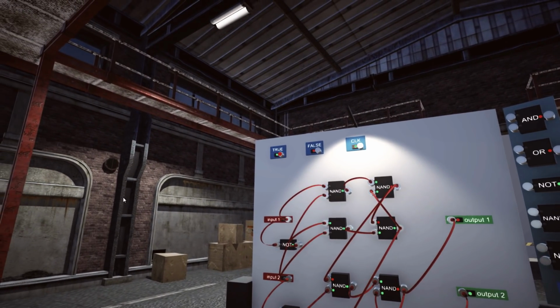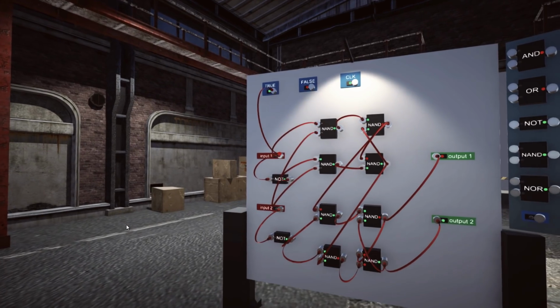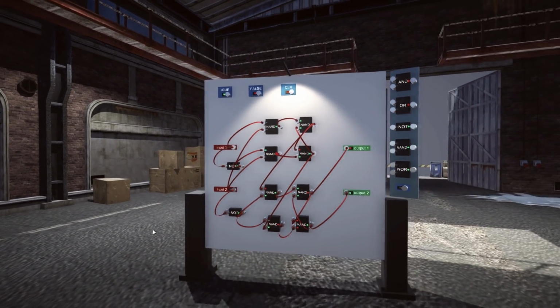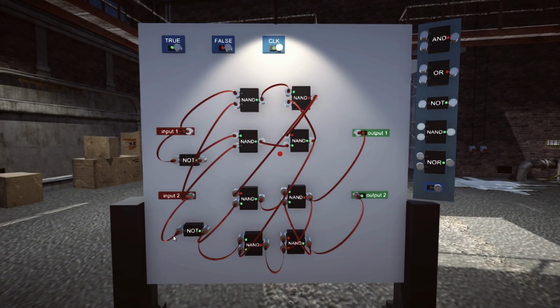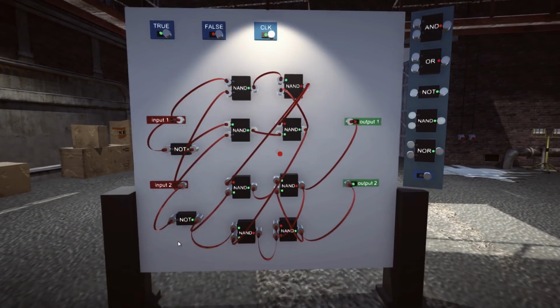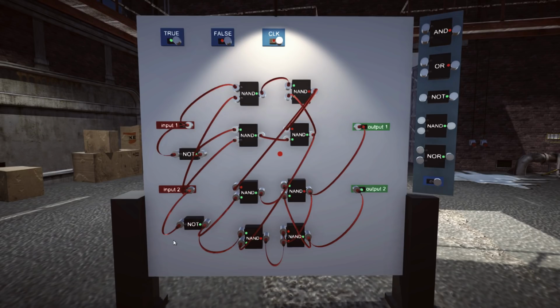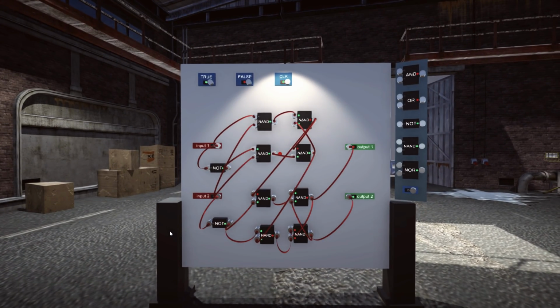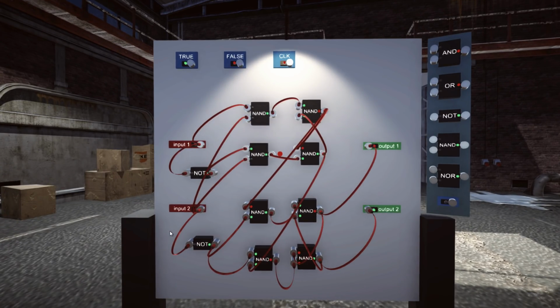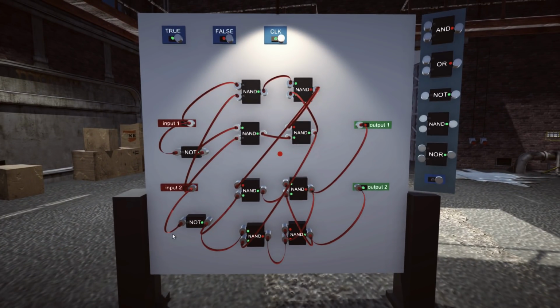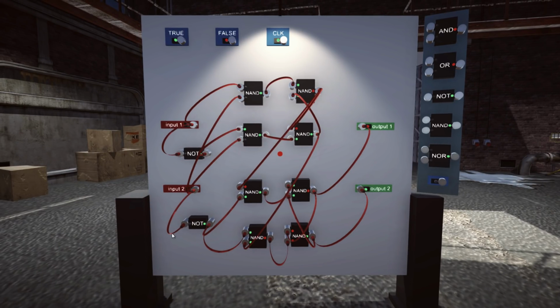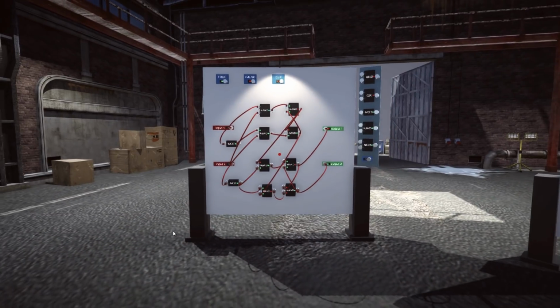And that's the idea. Like, you connect up inputs and you see what happens when I connect that input to here, because this first circuit is a clock ticked chunk of memory. Right? This is one bit of memory with a clock input, which is really fundamental to a computer. So you could do a lot of levels where you're messing with building memory banks that get bigger. Right? You start with 1 bit and then you make 8 bits. Right, and then you have to figure out how to get numbers into those 8 bits. Right? So if you wanted to save a number, an 8-bit number, it's just 8 of these in a line, chained in, and then you put the number in, and then you give it a clock pulse, and that number gets saved. Right, and that's now a memory bank.